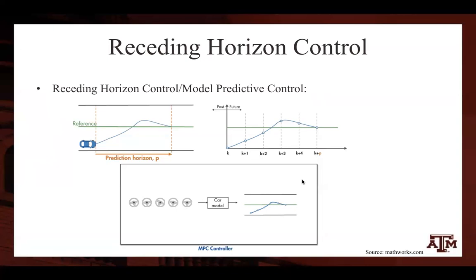The prediction path with the smallest cost gives the optimal solution and therefore determines the optimal steering wheel angle sequence that will get the car as close as possible to the reference. At the current time step, MPC applies only the first step of this optimal sequence to the car and disregards the rest. Based on the applied steering wheel, the car travels some distance.